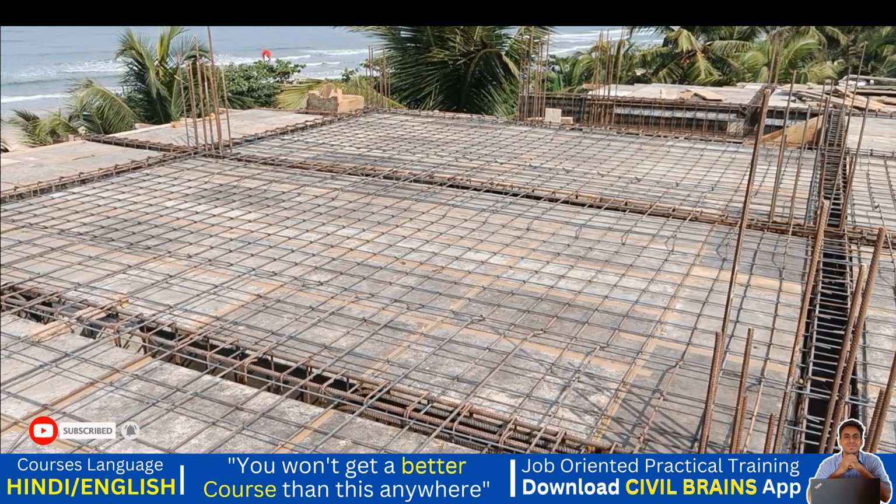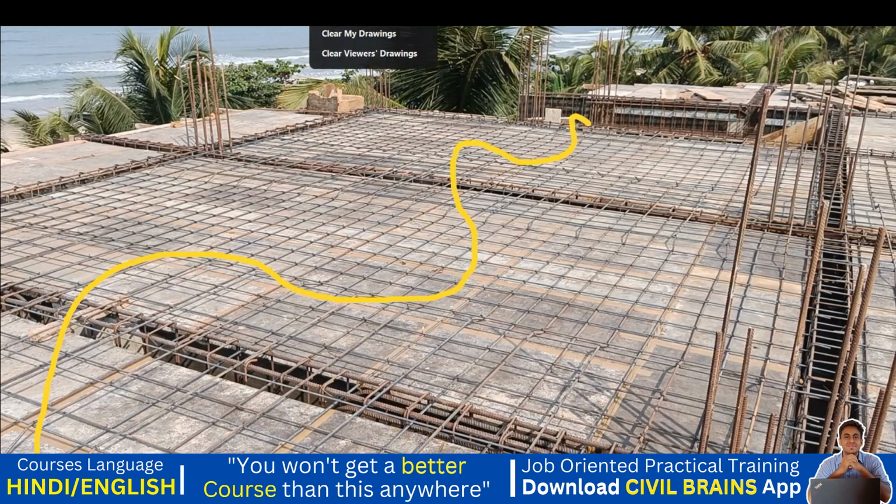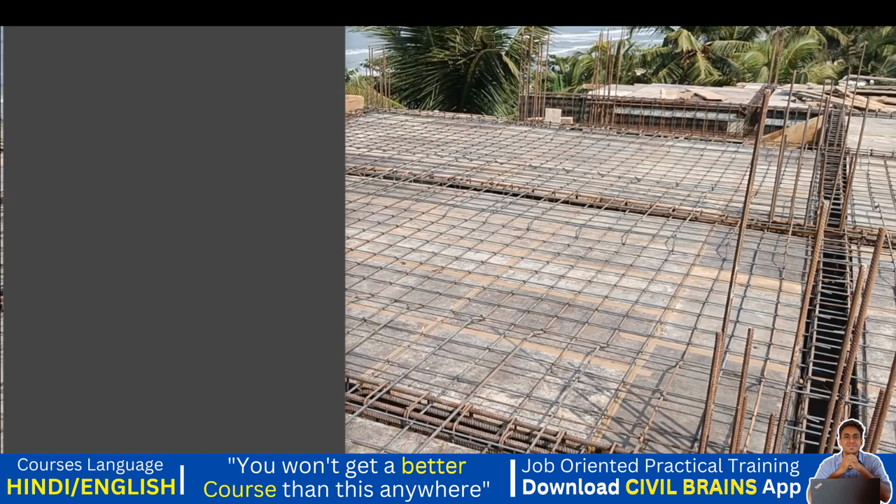If I pause it here, and if I ask you to plot a bending moment diagram, now you should be in a position to plot a bending moment diagram. So you should tell, sir, this is how the bending moment happens. We had a negative, a negative, a positive, a negative, positive and negative. So based on that only you can see the steel here. Here we have cranked the bar because we have taken the bar to the top. We have provided a bottom steel, that is a sagging bending moment, again negative, sagging and again negative. Got it?